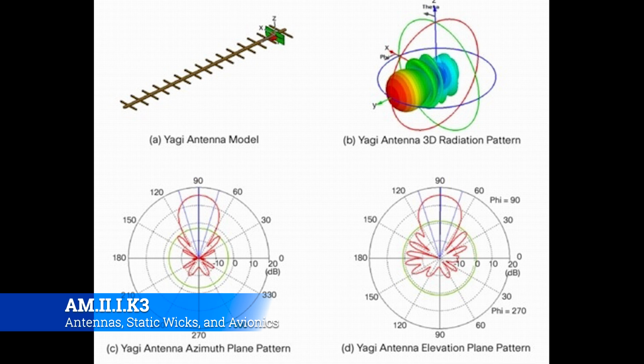Like if you have limited radio power and you know exactly where the person is that you're trying to transmit to, you might want to have that antenna set up on top of your shed and aim directly at the next place that you're trying to talk to and shoot that off. This isn't really that different from the way an ILS works. They have very specific antennas that shoot a very specific antenna lobe pattern directly to the airplane. The airplane just flies it on down.